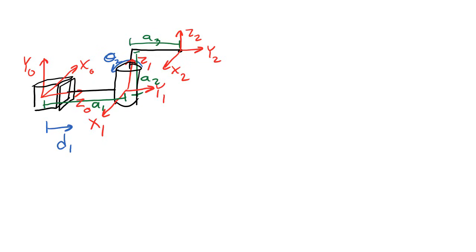Okay, let's do inverse kinematics for this manipulator. This manipulator starts with a prismatic joint and then has a revolute joint attached to it. Let's start by drawing this manipulator from the top-down view. From the top-down view, the first joint will look like a square. Then we'll have a circle for the second joint, and then when I show the last link, I'm going to draw it as though theta 2 was 45 degrees.